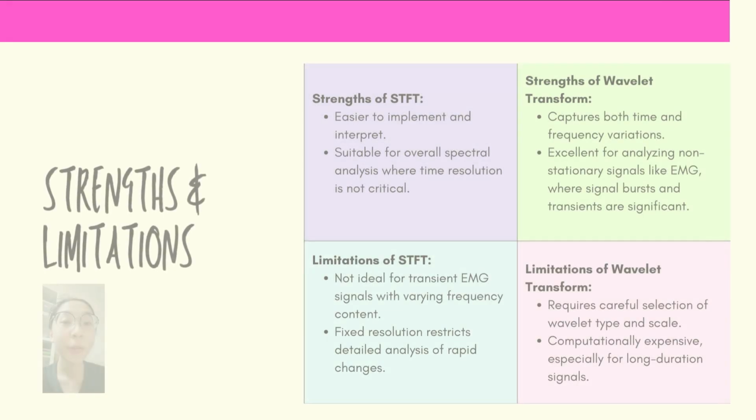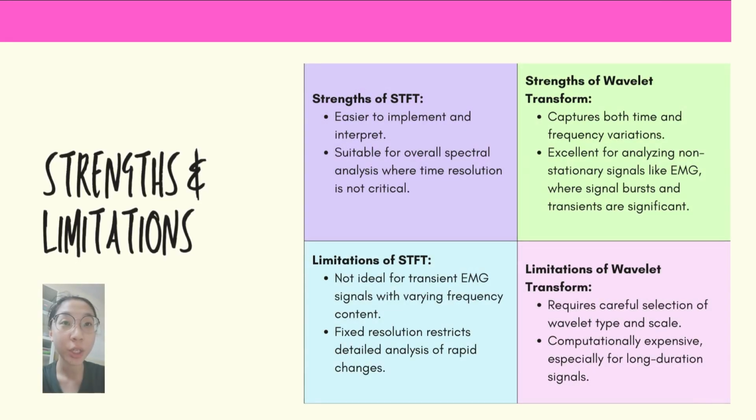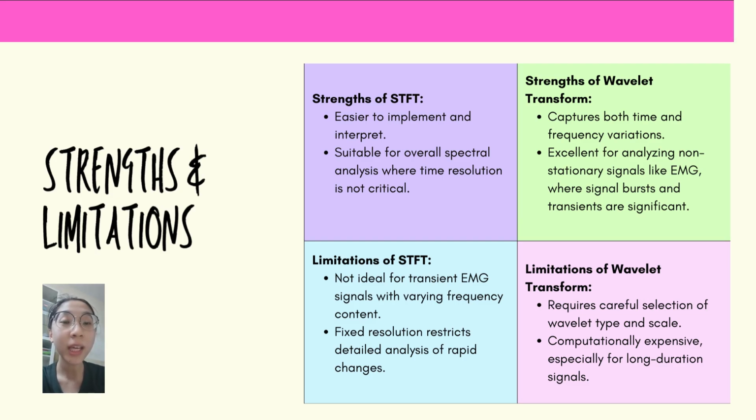For the next one, I will explain about strengths and limitations. The strengths of the STFT include being easier to implement and interpret, and being suitable for overall spectral analysis where time resolution is not critical. The strengths of the wavelet transform include capturing both time and frequency variations, and excelling at analyzing non-stationary signals like EMG.